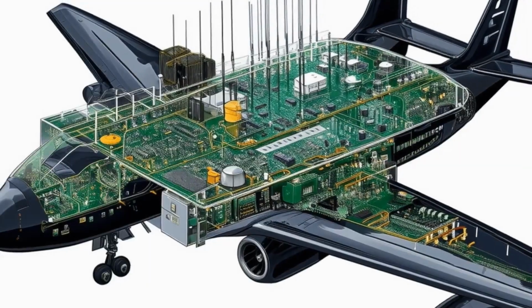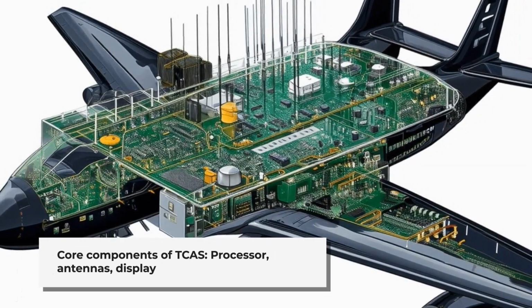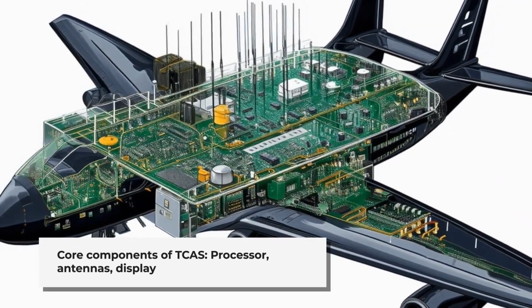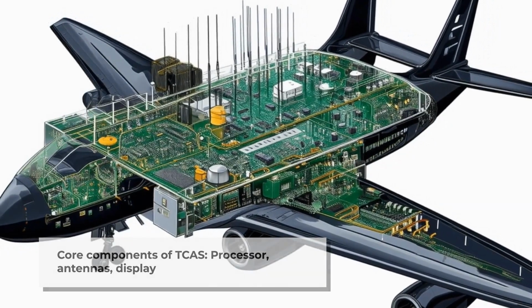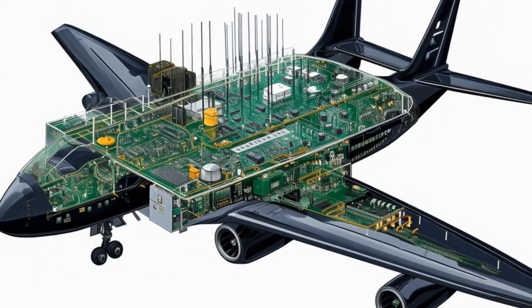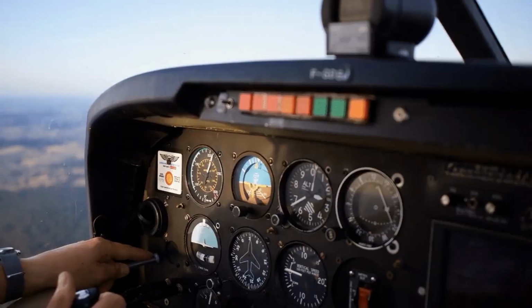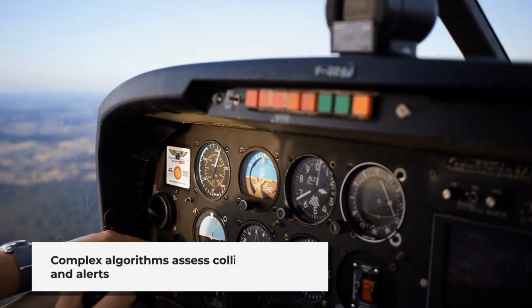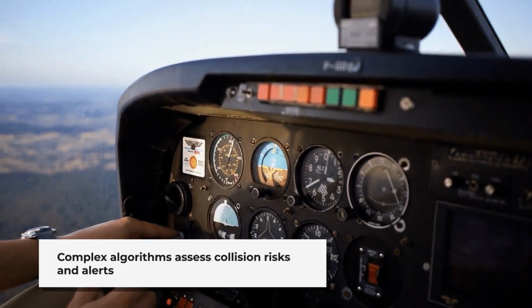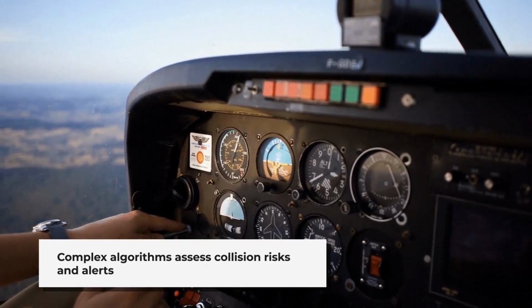Let's take a closer look at how TCAS works. At its core, TCAS consists of a processor, antennas, and a display system. The processor analyzes data from the transponders of nearby aircraft, while antennas send and receive signals. The system uses a complex algorithm to determine the risk of collision and generates alerts based on the proximity and relative altitude of other aircraft.